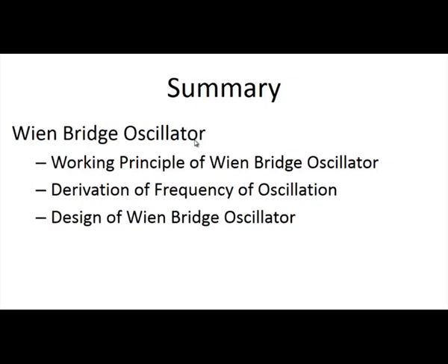There is no external signal given for an oscillator, only the noise is taken as the input, which is getting amplified and fed back to the input of the amplifier again and again. Since the amplifier is working in the non-linear region, the output will be a sustained oscillation. Even though the amplifier is amplifying the input, the output does not increase indefinitely. It gets sustained once the transistor goes to the saturation mode.